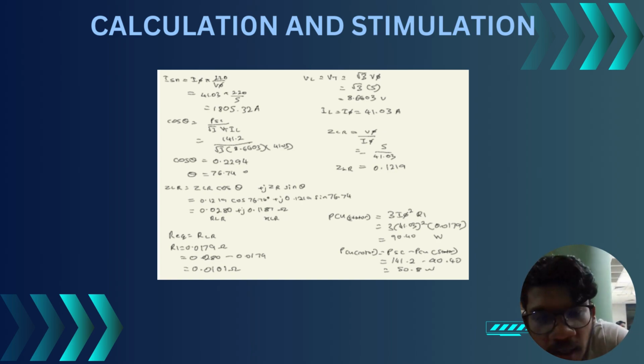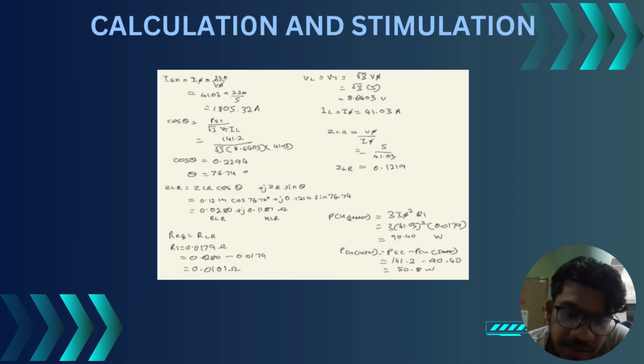In this calculation, everything we analyze reveals that RLR and XLR remain steady, the power factor stabilizes, and then the line current increases with the voltage. This circuit analysis indicates the equivalent circuit behaves similarly to a transformer, exhibiting minimal core or magnetizing losses. Overall, the calculation displays a linear relationship between the voltage and current with consistent impedance characteristics, confirming the motor starting characteristics, and then validating the theoretical prediction of the locked rotor condition, with the total impedance maintained at